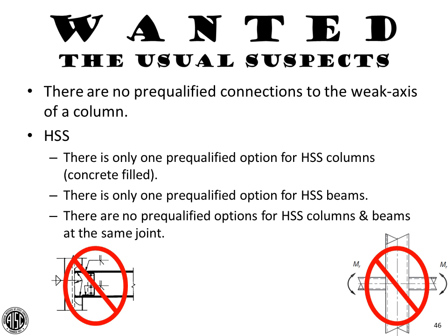Another thing that sometimes we get questions about is that these column sections, these built-up sections, are assumed to be prismatic, so you can't just provide the reinforcing or that section over a small length of the column. It's intended to be over the entire length of the column.